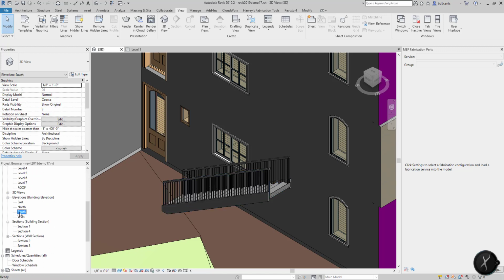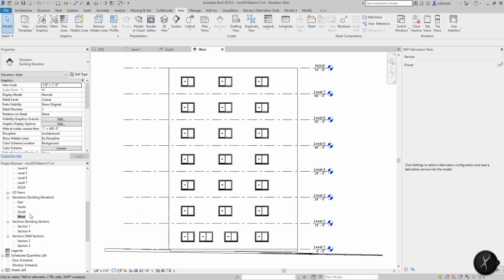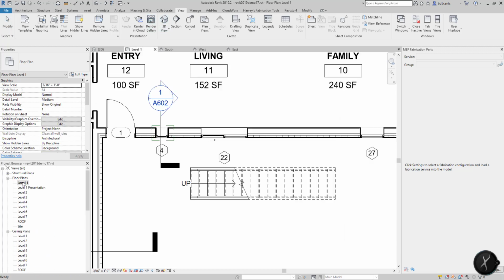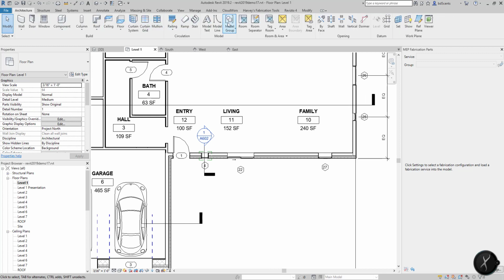We're going to go to View, 3D, and in 3D you'll notice that I have a set of stairs. You'll also notice that that updates my south view as well as my east view. So we're going to go back into level 1, and now we're going to delete these stairs, and we're going to create a new set. We're going to create a U-shaped staircase.